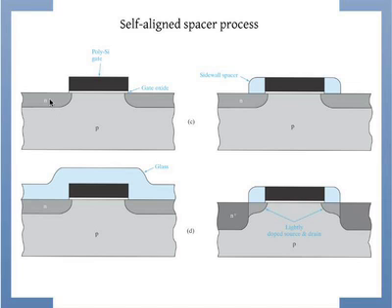So the idea is very simple. Let's say you have an N-type source, N-type drain, and your gate is defined there. What you do here is you grow oxide, silicon dioxide or glass, everywhere, it's all over the place, and then you do what's called an anisotropic etch, which means that the etching happens only in one direction, vertically, straight down.